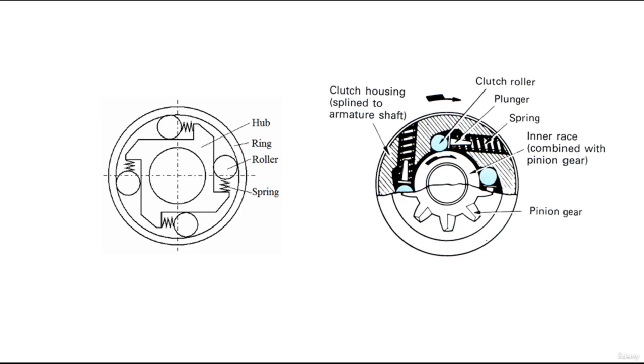If the vehicle slows, engine speed also slows along with the turbine speed. This decrease in turbine speed allows the oil flow to change direction. It now strikes the front face of the stator vanes, halting the turning stator and attempting to rotate it in the opposite direction. As this happens, the rollers jam between the inner race and hub, locking the stator in position. In a stationary position, the stator now redirects the oil exiting the turbine, so torque is again multiplied.